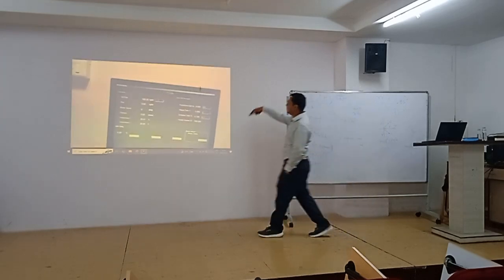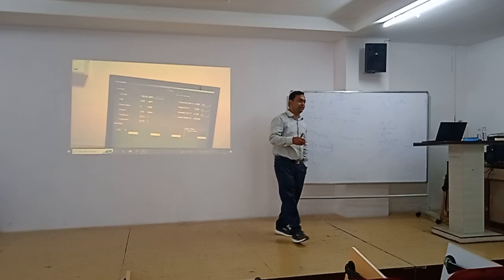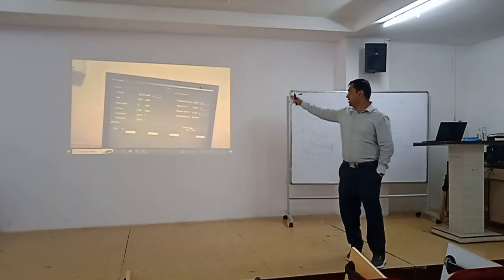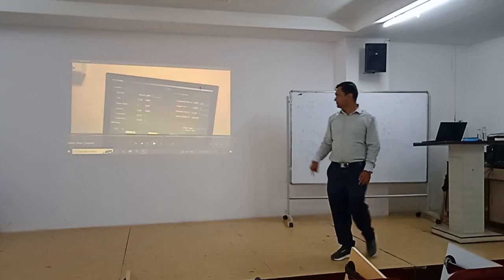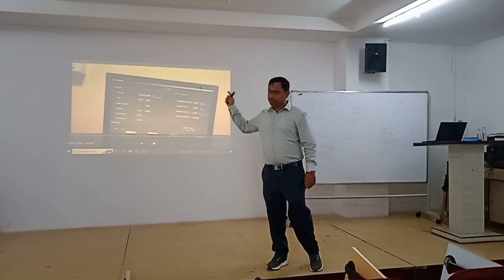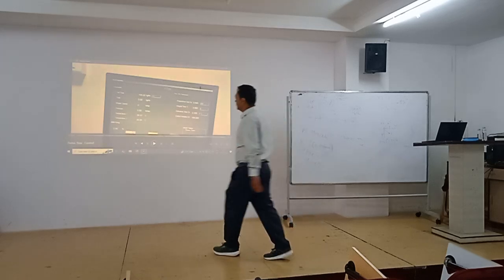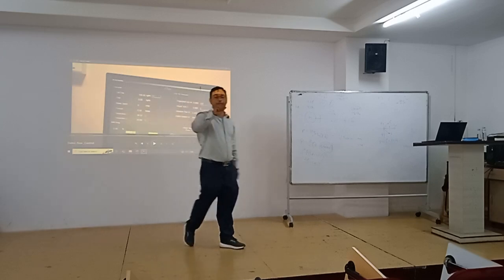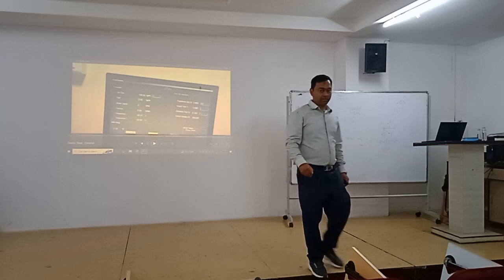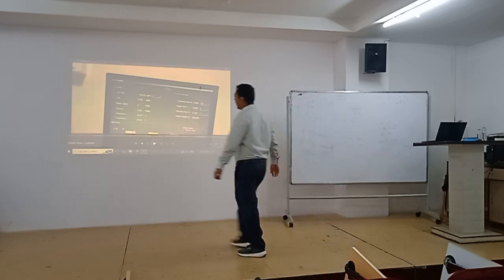So we can do this many things. We can control the flow, the speed, and the temperature. First we are controlling the flow. This is the SCADA where we are entering 100. Set flow means the water flow that we want from the system, which we put as the set flow. And this is the actual flow.